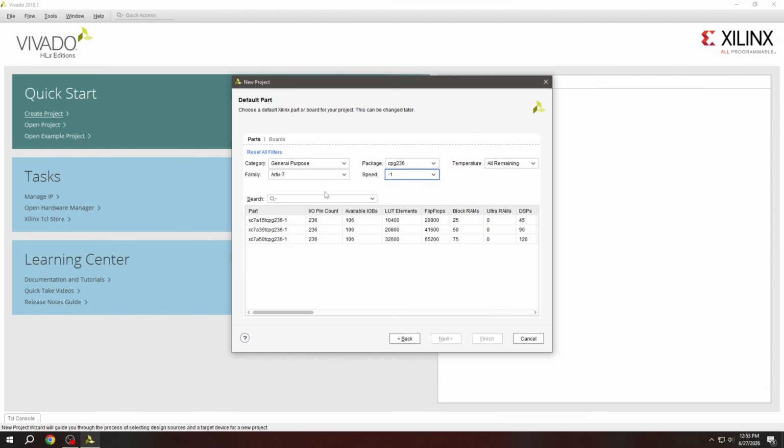And second, I'll show the LUT elements. LUT stands for lookup table, and this is very important for combinational logic. FPGAs don't have permanent physical AND gates or NOT gates. Instead, they use the LUT to store a truth table and simulate gate behavior.